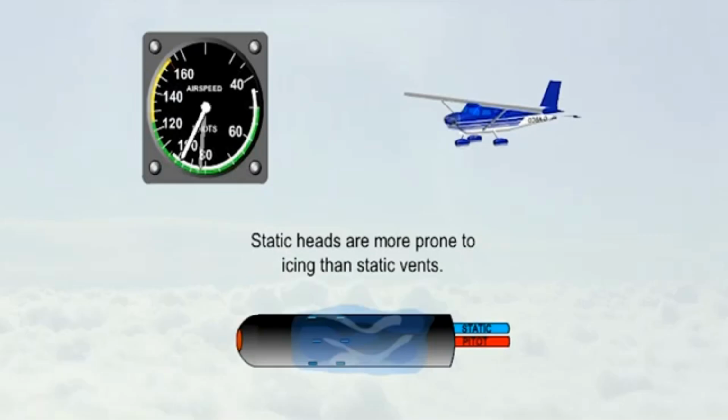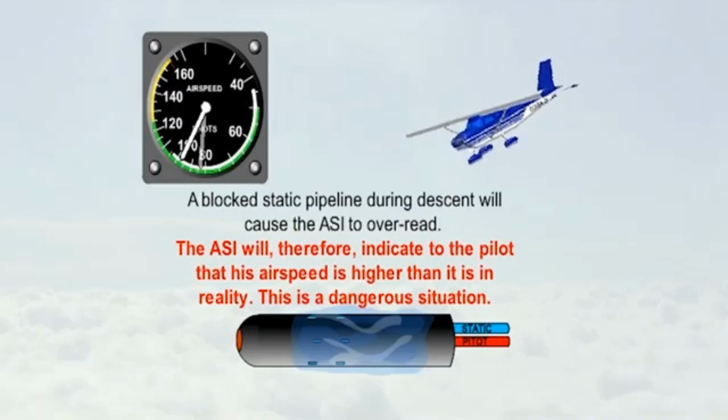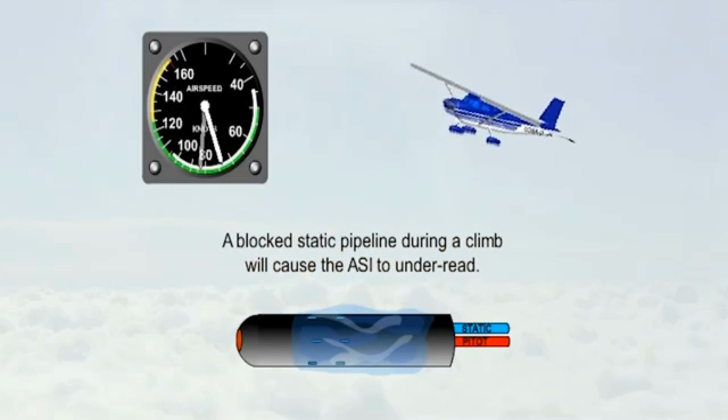A static head is more exposed to icing conditions and is therefore more likely to become obstructed than is a static vent. A blocked static source during descent will mean that the old, higher altitude static pressure surrounding the capsule will be lower than it should be, so that if the pitot pressure is normal, the airspeed indicator will overread. This could be dangerous, in that the aircraft is nearer the stall than the airspeed indicator is showing. Note that a climb with blocked static source and normal pitot air will result in the airspeed indicator under-reading.